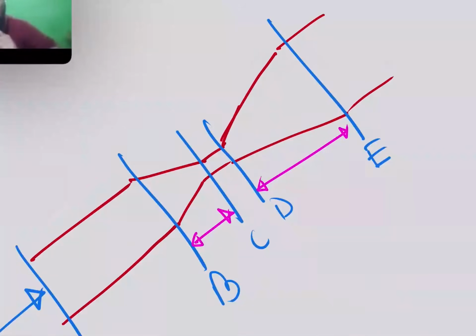To graduate the diverging part from the throat, we have to diverge the section in such a way that no adverse pressure gradient or turbulent eddies are formed, due to which there might be some inaccuracy in the measurement of flow. That's why we diverge it in a long section.